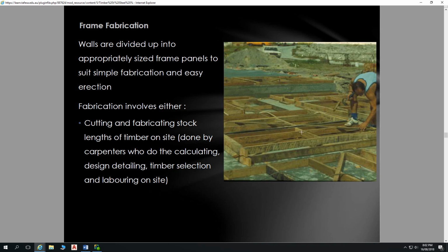But look, timber bracing as well. That's something you really will not see. But essentially, much of this has not changed. So we've still got our studs at 600 centres. We've got our noggins between those. We've got our top plate and bottom plate. We have our frames built on top of the slab and then tilted up. That's how it happens. They're all laid out now.